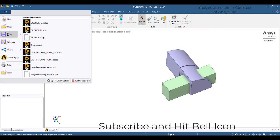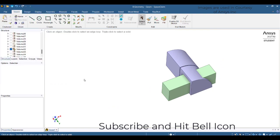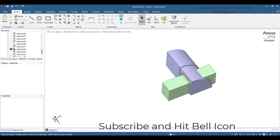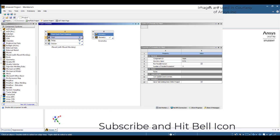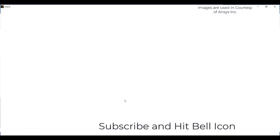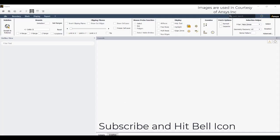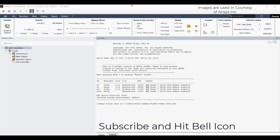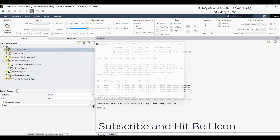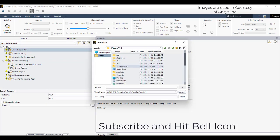Now go file, save as muffler silencer 3. So this is helpful in getting the body of influence. So only in that body we get a body of influence option, and it will influence and create the mesh. So reset this. Okay. Go to mesh, double click the mesh option, start it. So now on starting, we'll try to import that. So go to geometry, import geometry, and go to downloads,